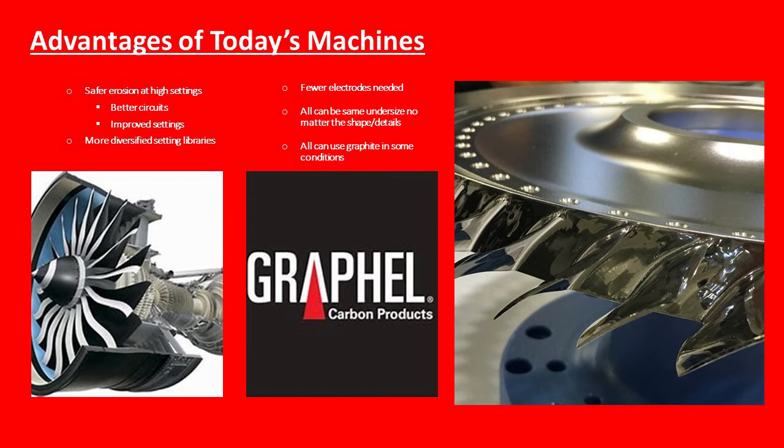There's better circuits and improved generator settings that monitor the spark gap and give constant feedback to the system to let it know if something bad is happening. I mentioned the more diversified settings libraries for different alloys, carbides, things like this. Makes the machines extremely versatile. You could go, for example, from burning a mold insert, if you're a job shop, to burning an aircraft engine part of Inconel, and then switch over to maybe trying to burn some carbide for another customer. So just diversification across the line on one base.